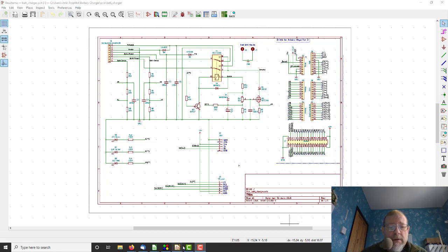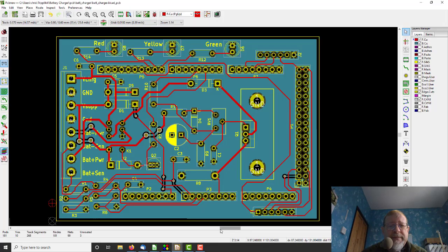So if we go to the PCB, here it all is, and I've added some labeling on the terminal block here, and on the LEDs, and shuffled a few things about and relaid it out. Oh, and I've left 1mm round the edge with nothing on it. It doesn't actually say on the website if you should or should not leave a gap round there, but 1mm seems like a good amount.